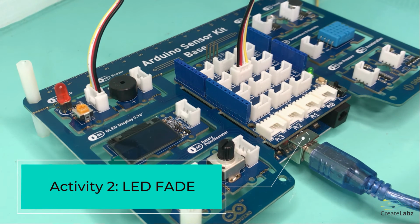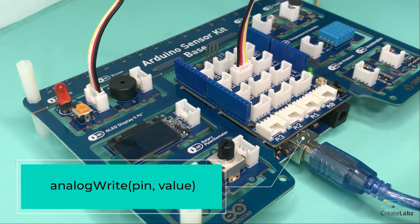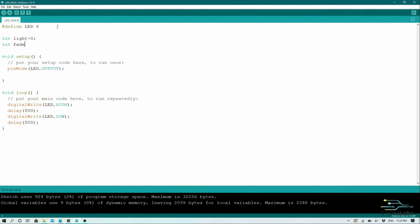The second activity we will be doing today with our LED is LED fade. What this activity does is it introduces the use of the analogWrite function. This function uses pulse width modulation, thus turning the digital pin on and off very quickly to create a fading effect. Here we introduce new variables, light and fade, where light is the amount of brightness of the LED and fade holds the value to fade the LED by. This becomes understandable once we see the main code.